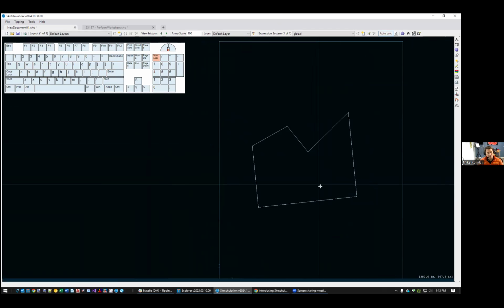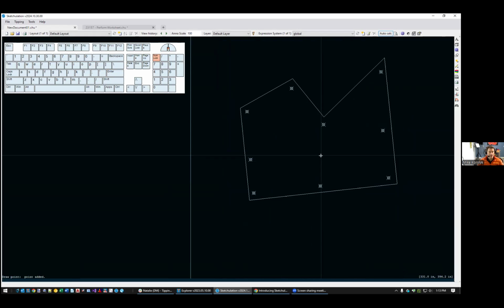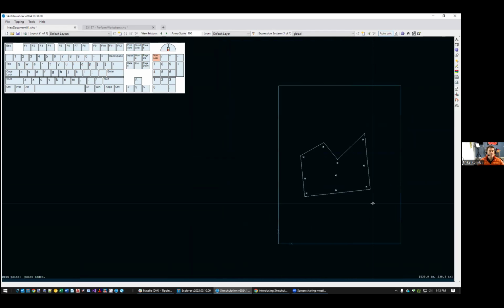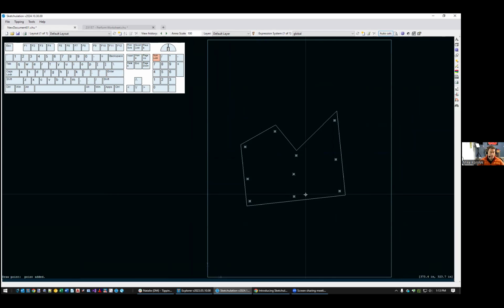What you need to do is you have your floor area shape, and then you have a set of points like this. I'm just going to plop in some points in some roughly random locations, but somewhat reasonable from an engineering perspective. Something like this. Maybe that's your column layout. Maybe we need one more in the middle here. And so then what we want to do is mesh this shape and include the points.